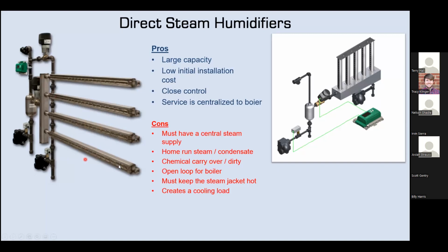The other approach is to use one control valve and put steam into a header where the pressure is reduced to atmosphere, and then that steam will come out of these nozzles just as though you're producing it from a steam generator. A benefit to this style is that you can have insulated grids.